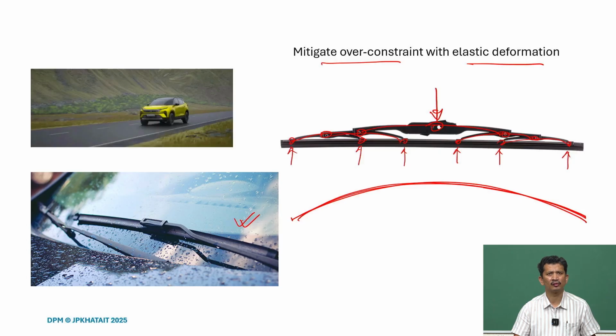So, if we are aware of these methods, many times we can replace the expensive items with monolithic designs, with plastic injection molded parts, with proper design of the hinges, and we can get the same kind of performance.